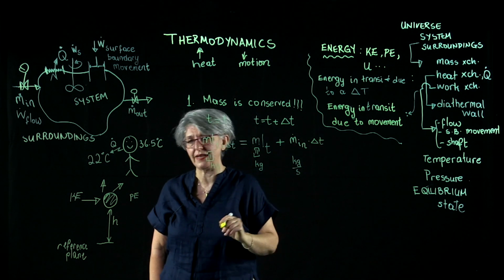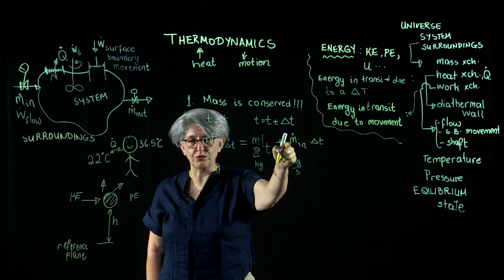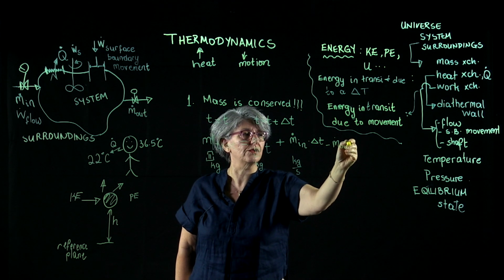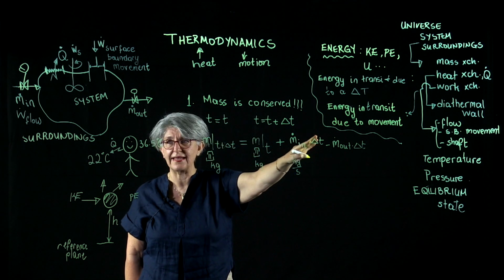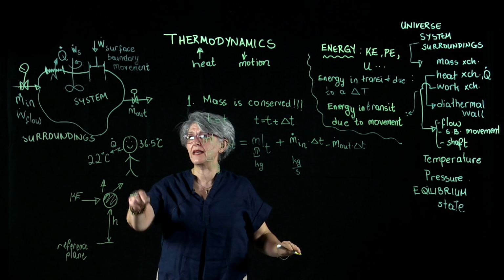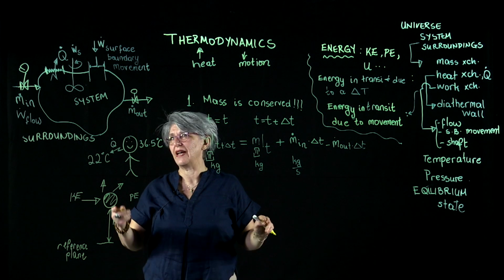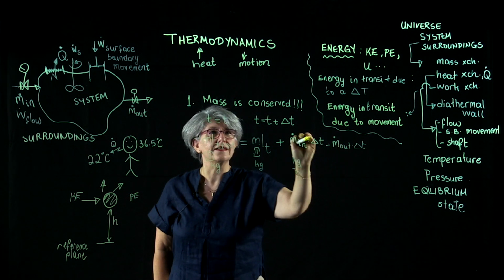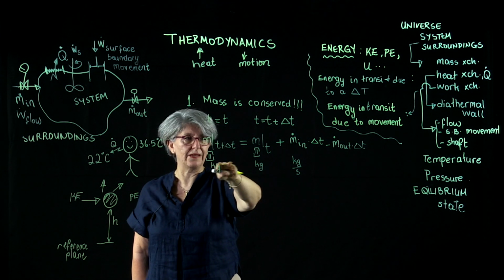I have to multiply by delta T. This amount of mass entered through my system boundaries minus m dot out times delta T. That much mass has left my system boundaries in the meantime. And as far as my system potato drawn as such, I only have m dot in and m dot out. And this is my conservation of mass equation.